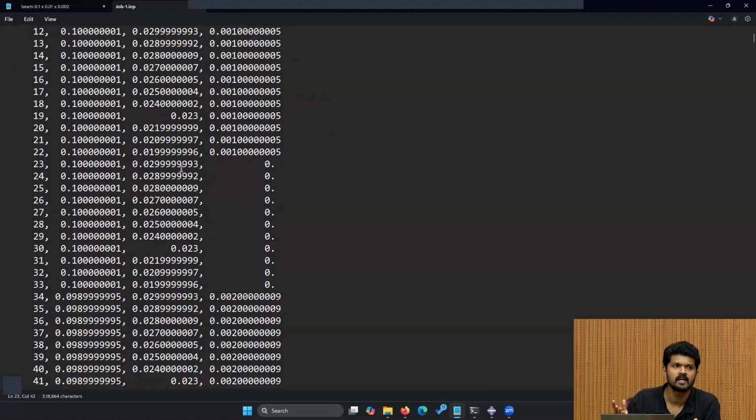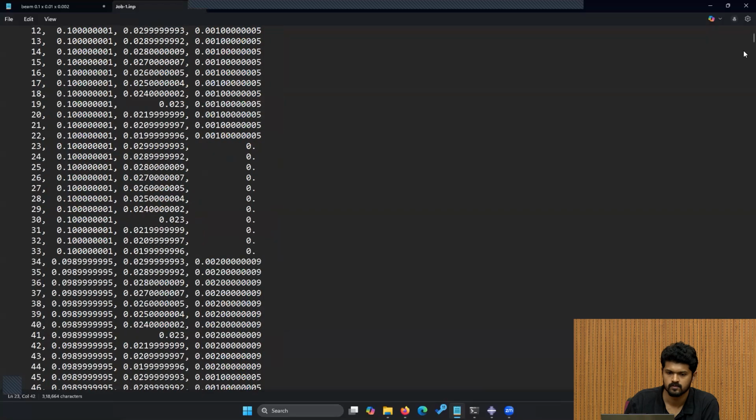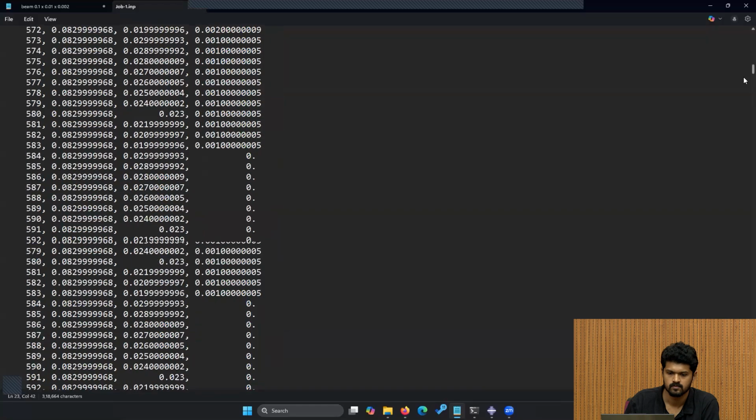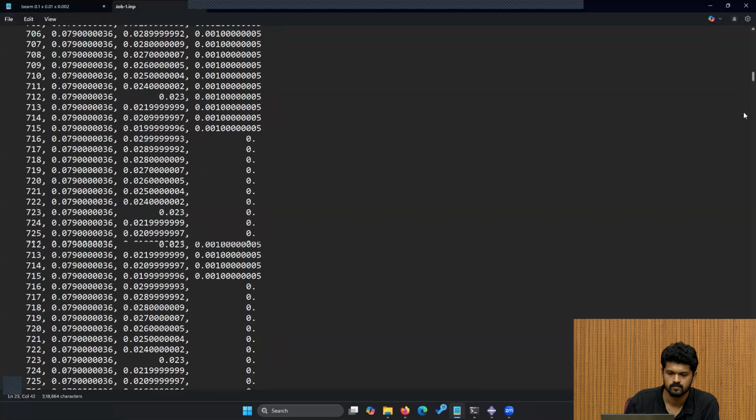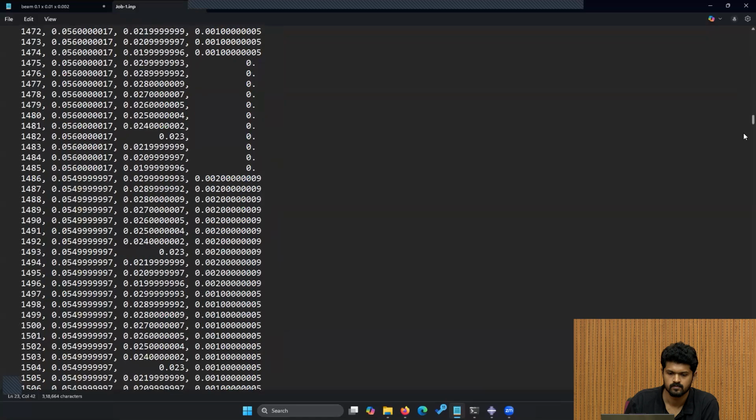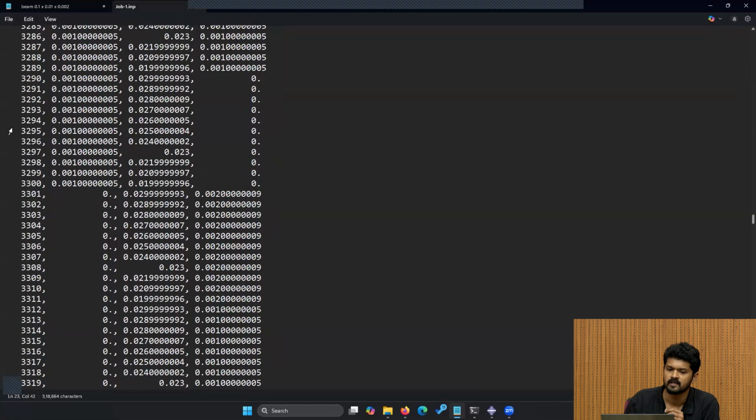When you write a finite element code in MATLAB, you will define the geometry, you will define the nodes, and you define something called a connectivity matrix. The connectivity matrix will tell you which nodes an element connects. This is the nodal information, and this is the element.